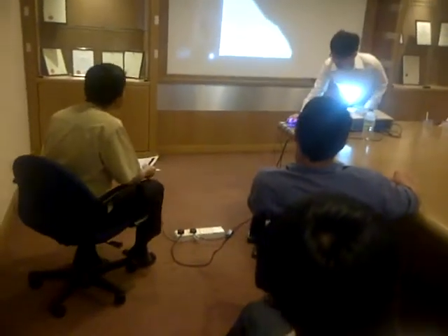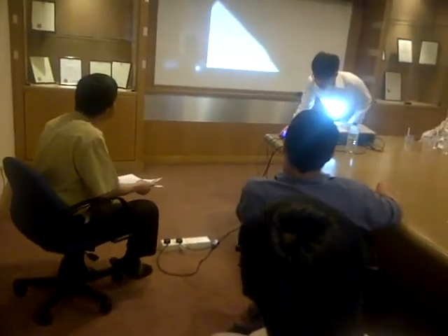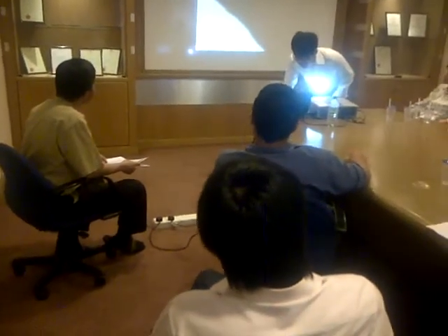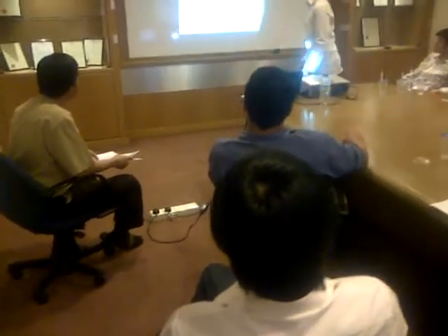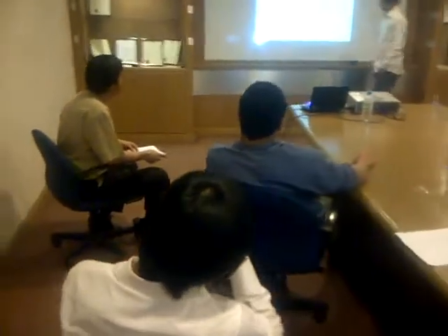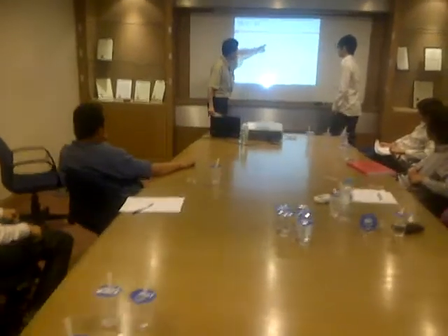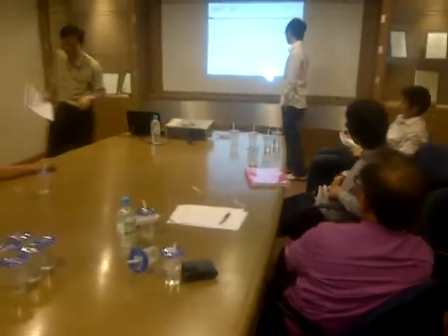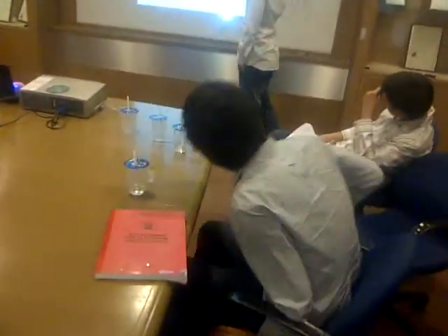Then to another DB, the second DB will be just served for the switch socket outlet. You have to understand, this cable and this cable are inside the DB. Yeah, very short only. Okay, continue. It is just served for the switch socket outlet.